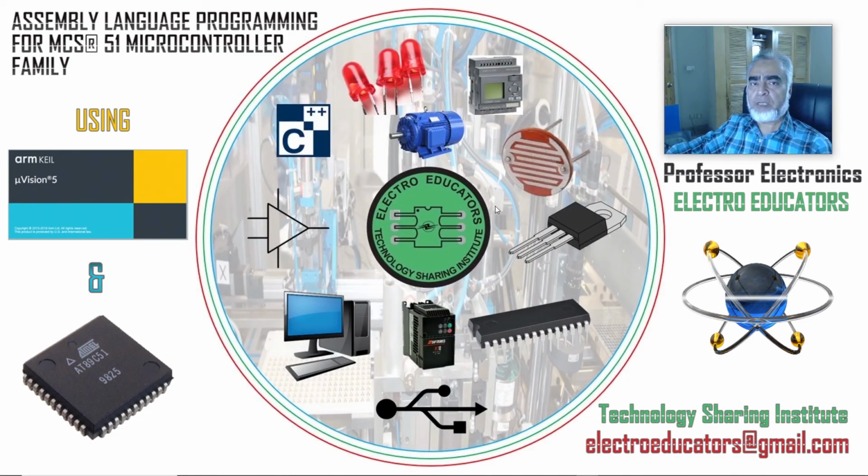In our previous session, we developed a program to run a counter manually using switch 1, which is connected on port 2.0. In this session, we will add a subroutine to reset the counter, because in our previous program there was no reset input and we were not able to reset the value of the counter. Now we will add a reset input and write a reset routine for our counter